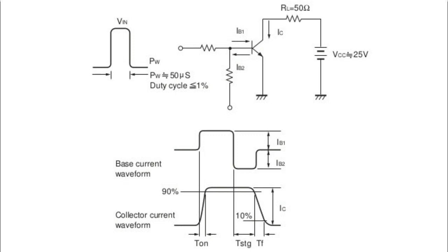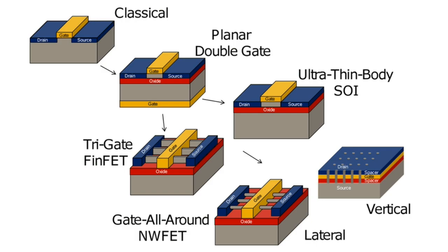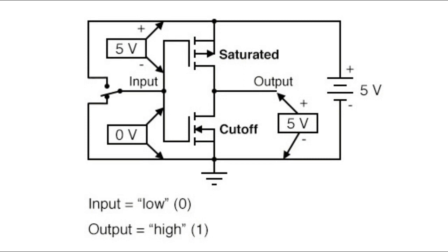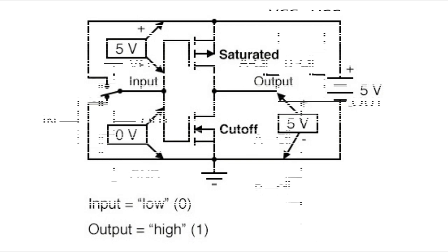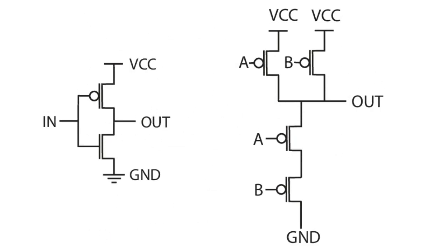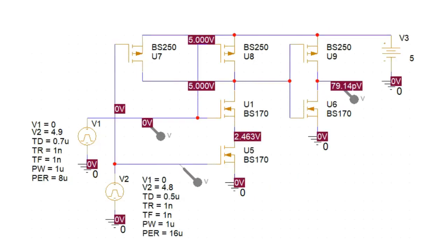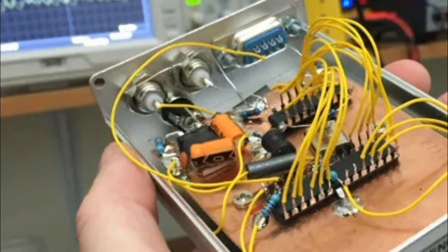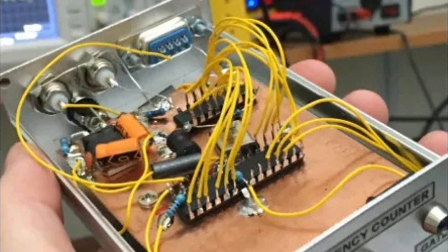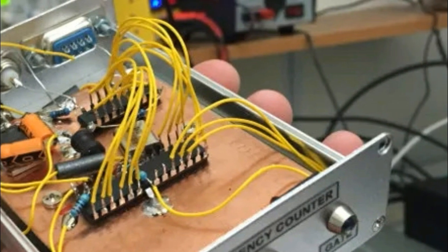To overcome these limitations, complementary MOS, called CMOS (complementary metal oxide semiconductor) logic gates, which use field effect transistors, or FETs, were developed. As these gates use both P-channel and N-channel MOSFETs as their input device, at quiescent conditions with no switching, the power consumption of CMOS gates is almost zero, 1 to 2 microamps, making them ideal for use in low-power battery circuits, and with switching speeds upwards of 100 MHz for use in high-frequency timing and computer circuits.